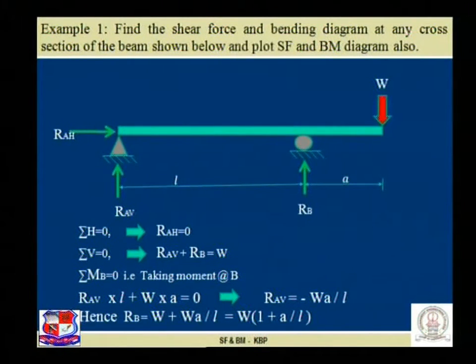See the kind of beam which has been given to us. The beam holds one end or both the end projected beyond the support. This is my support. This part is projected beyond the support. This beam is referred to as a one-way overhanging beam. This beam is subjected to a single simple point load W at the tip, at the free end. The span between two supports is L and the overhanging projection has a span of length A.